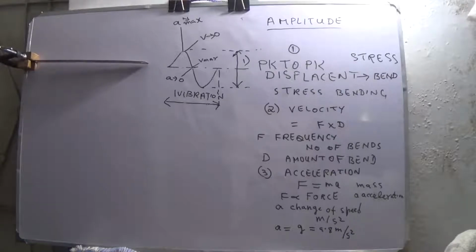But we will look for faults by means of vibration frequency when the vibration limit is exceeded, because there will always be some amount of vibration, but when it goes beyond the limit, then we are worried and we will look at frequencies to find the fault.